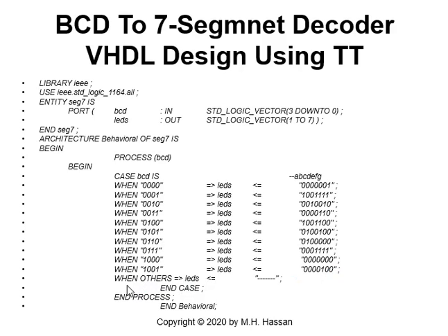Now, all the others, they are don't care, so we will assign the LEDs seven dashes, which is the indication for do not care. I don't care what value is assigned if another input occurs outside the zone between 0 to 9. This is a non-BCD input, which will not usually take place. So the LEDs will be assigned don't care.